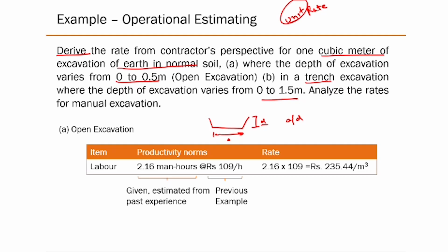So in that case, you don't need to worry about preparation of the soil, or about putting some sort of formwork to make the soil stable, because you expect that this is not going to cave in. What happens in excavation is that the soil you have excavated, because of the overburden pressure from the surrounding soil, can cave in, and that's a safety hazard. Your work will also not be effective, because the material is going inside again.